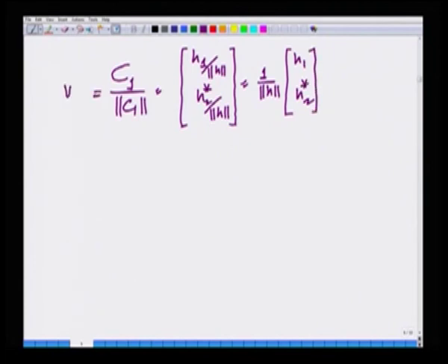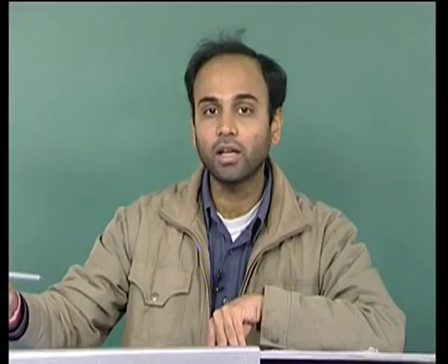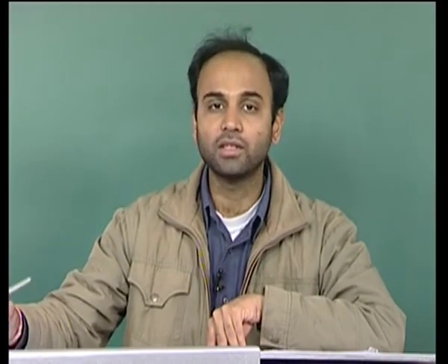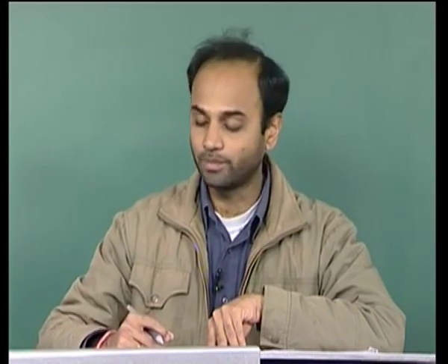We can also denote this as the beamformer W1. So, W1 is nothing but H1, H2 conjugate, that is column 1 divided by norm of column 1. Now, norm of column 1 is nothing but norm of the vector H1, H2 conjugate, which is norm of the vector H1, H2, which is norm of the vector H, where H is the vector H1, H2. For convenience, we can represent it as norm of H, since it is the same quantity.